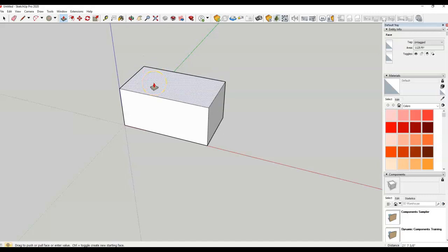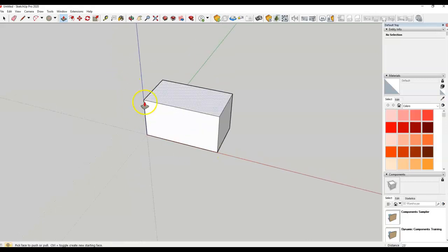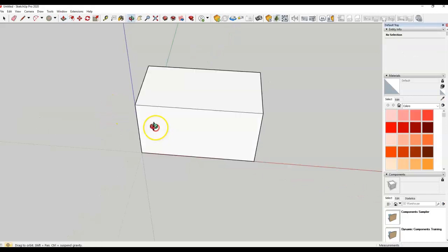And I'm going to set it to about 25 feet tall. So it's going to allow my floor to floors to be generous, but not ridiculous. Again, I'm sort of thinking about how tall a house might be. And as we'll see, there'll be a shed roof on here, and that's going to allow for that accommodation. But making a rectangle, super simple. Draw the square, push, pull it up. That's the power of SketchUp here.